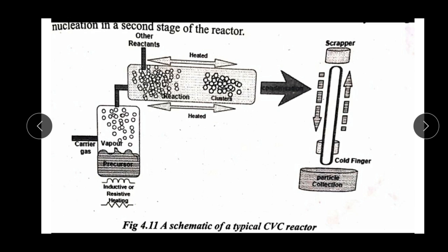In addition to the formation of single phase nanoparticles by CVC of a single precursor, the reactor allows the synthesis of a mixture of nanoparticles of two phases or doped nanoparticles by supplying two precursors at the front end of the reactor, and coated nanoparticles, that is zirconium oxide coated with aluminum oxide or vice versa, by applying a second precursor at the second stage of the reactor.